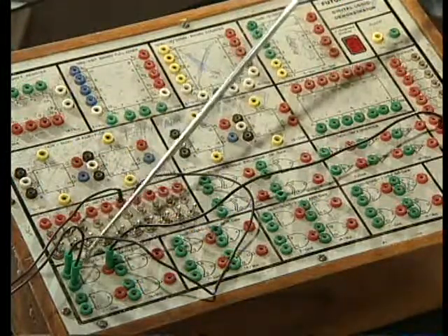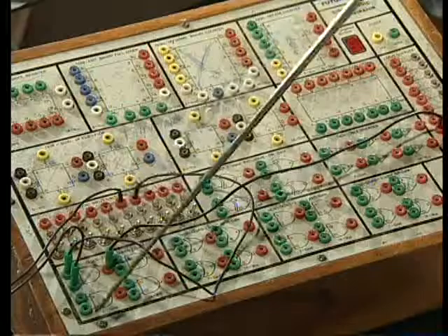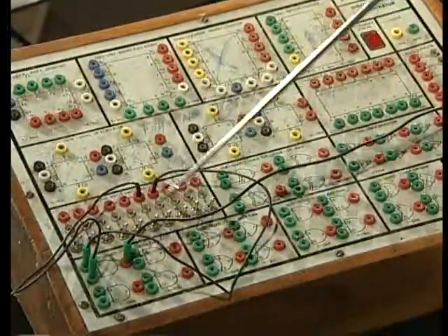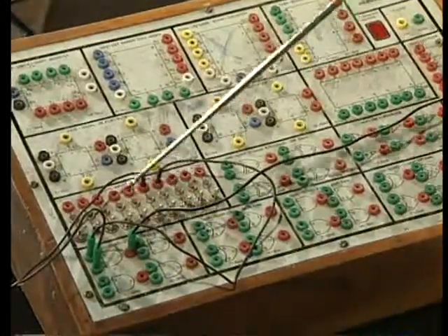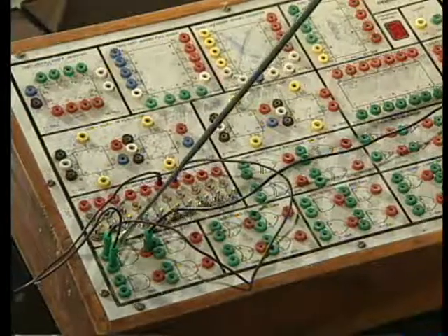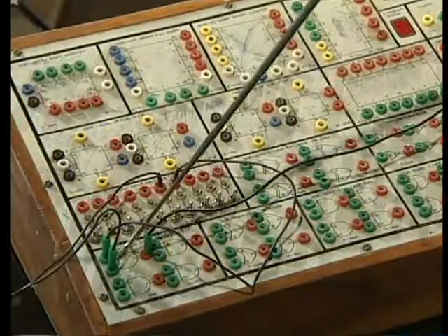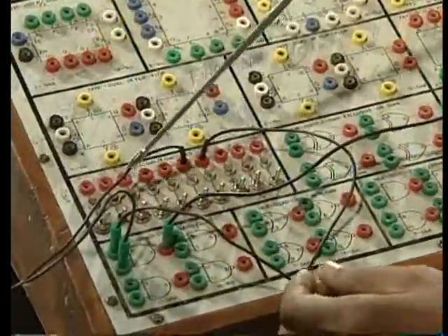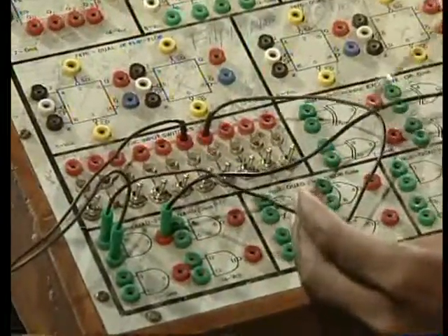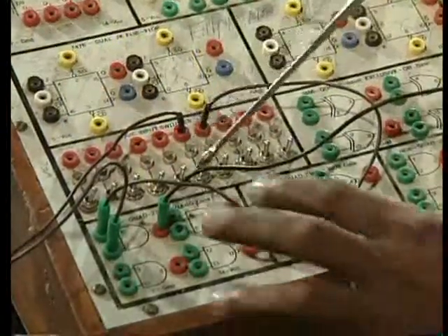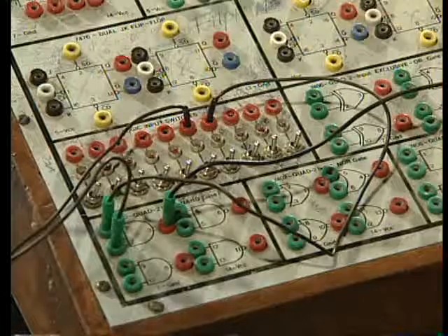This is IC 7400. This entire block contains IC 7400 that contains 4 2-input NAND gates. So, we shall select one NAND gate among them. So, here is that NAND gate, 1 and 2 are the input terminals and 3 is the output terminal. To these input terminals we apply the input from the input slots and the output is verified at the output slot.